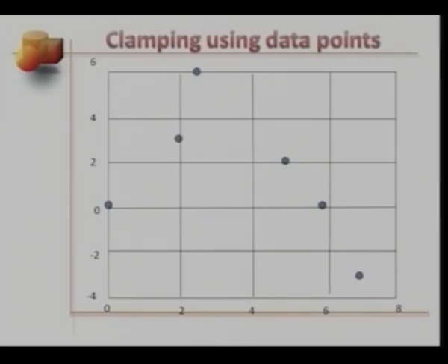Two design points coinciding, three design points coinciding. The multiplicity of this control point is 3 in this case. So remember, we are working with p minus 1 multiple design points. It's because of this that our new B-spline curve passes through the first design point.